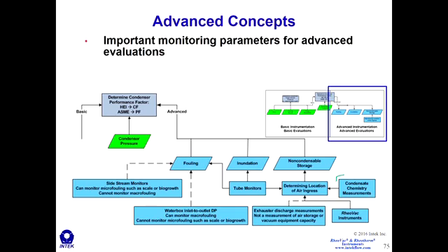Also, condensate chemistry measurements can help identify air in-leakage and identify the location of air in-leakage. And so I'll spend a few slides talking about condensate chemistry measurements, how to interpret them, and the reason for air in-leakage affecting some of those measurements. It's good to have a fundamental understanding of how condensate chemistry measurements can help you troubleshoot and locate air in-leakage.